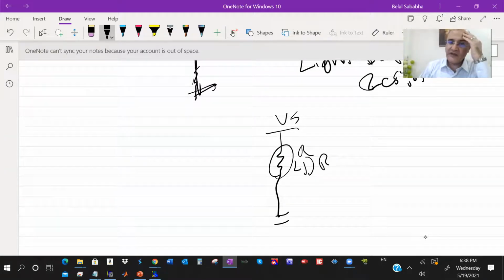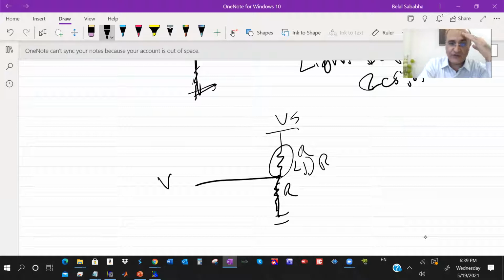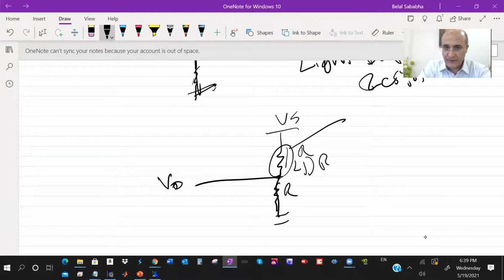Let's assume it increases. If it increases, you will have to have another resistor here to protect, right? And you can take this voltage from here. So when this is very low resistance, you're connected to 5 volts. When this increases with light, more resistance, the voltage drops down.